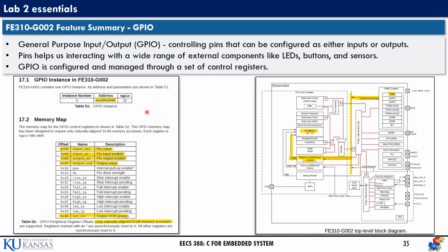As we have 32 pins from GPIO, we have to tell the CPU which pin we want to enable, and whether we are considering that pin as an input or output. And if we consider that pin as an output, what should be the value of the output, or what we are trying to pass through that output pin, etc. As I already told you, those pins are connected with the CPU using some registers.